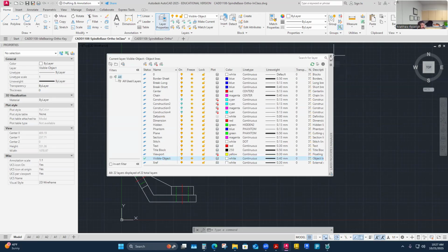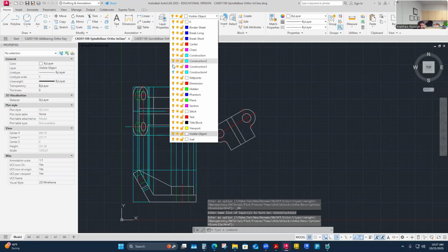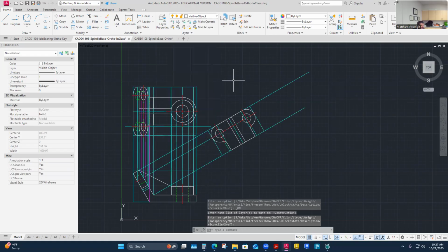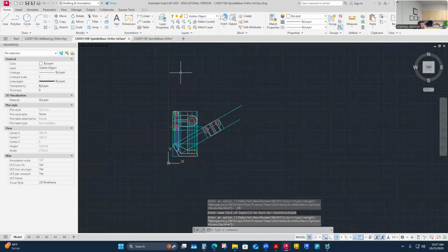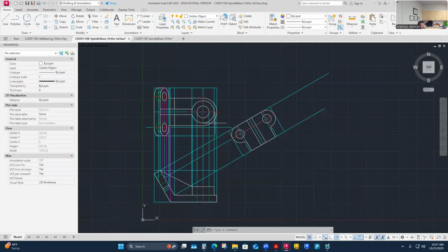So I would still have it as reference material if I needed to make a modification. Because I feel like these are my master views, and I wouldn't want to just delete them or get rid of them. All of the construction work is based off those views. So they're pretty important. Once I make a copy to a view here that I'm going to dimension, that's great. But if I ever have to make a revision or modify that, this is what's holding all the information, and it might be what shows my mistake that I made.